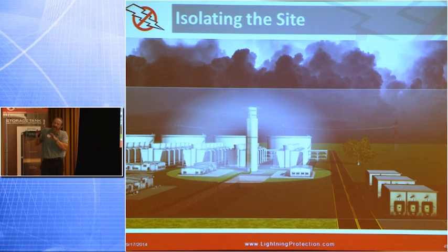As the storm moves into the area, the electrostatic fields grow slowly over time, and we start to bleed off that charge. We're letting electrons flow. Remember, electrons: not enough over here, too much over here. I have too many protons down here. I need a free flow of electrons, a slow, controlled, methodical flow, to neutralize that charge. So I'm slowly, continually allowing a free flow of electrons from an area that has too many to one that doesn't have enough. When I neutralize that charge, I've created what we're going to call a space charge, a corona cloud. And that's the gray area here.